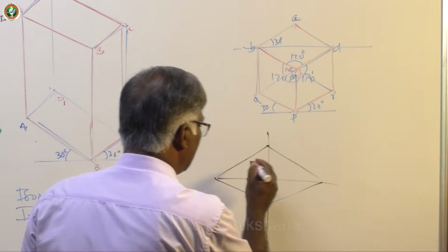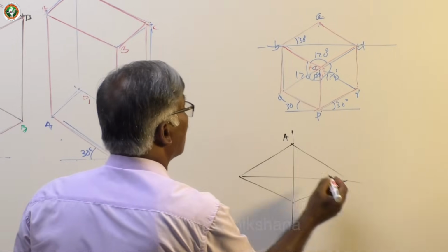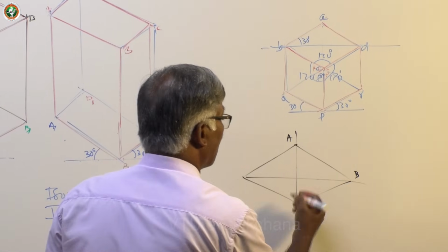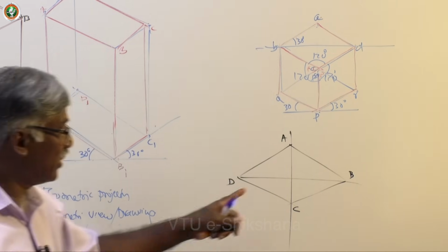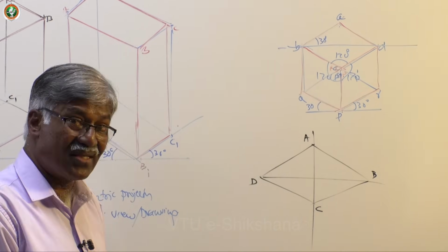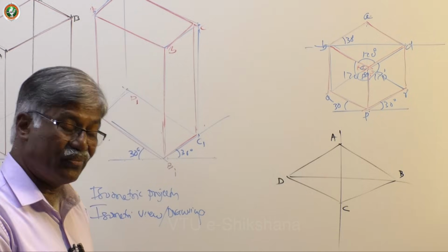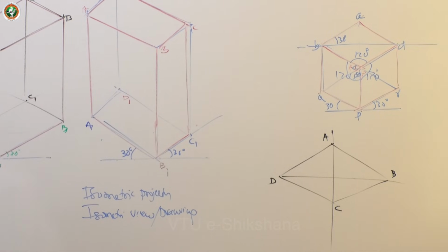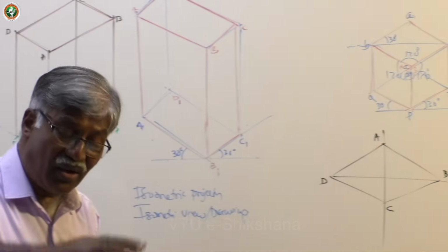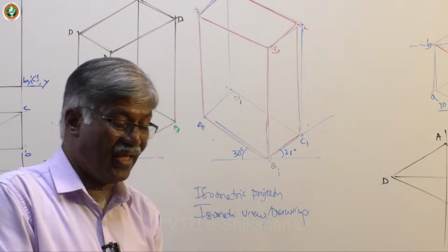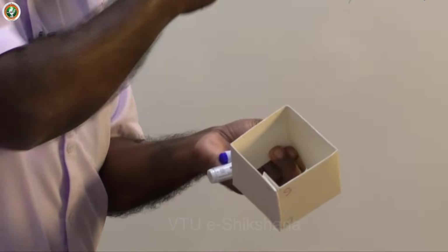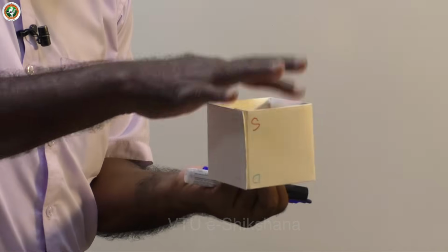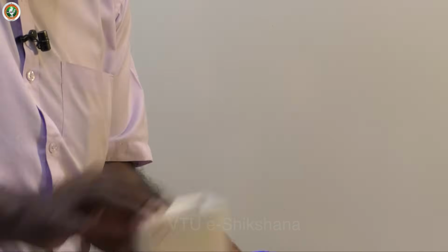Okay, this is say A, this one is B. For explanation purpose, I am changing it. ABCD is the isometric projection of the top face, when it is having the body diagonal perpendicular to VP and parallel to HP. When it is parallel to HP like this, in this corner condition, in this condition ABCD is the figure. In this condition AC never changes distance, AC remains same.